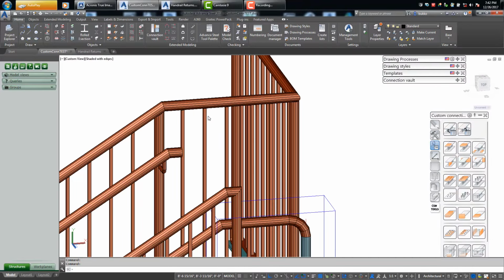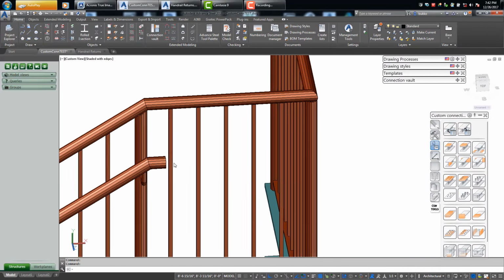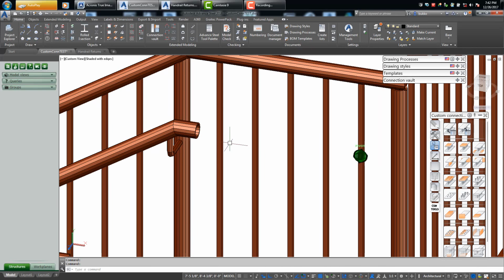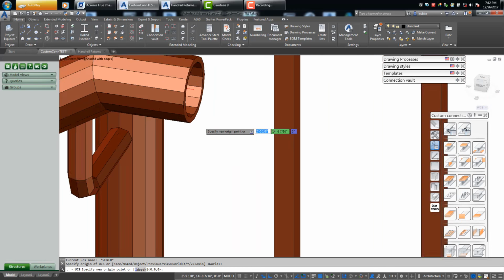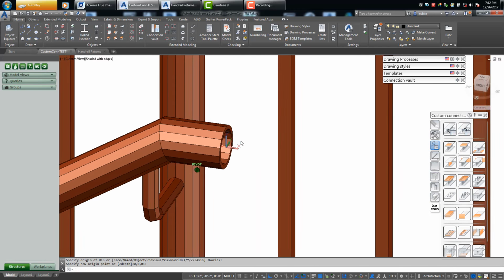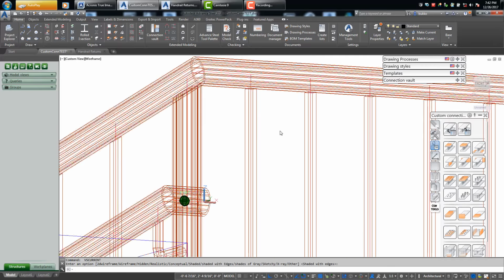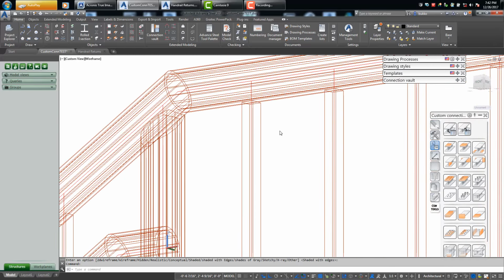Now this one right here, if I want to create a return that's basically connected to a plate that's welded between these two pickets, there's a way that I've got to do this, and I've got a custom component created. What I'll do here is take the UCS, place it right here, and I've got a little alias set up for my snap. So I'm going to go ahead and activate the 2D snaps on and change the wireframe mode so I can see it a little better.